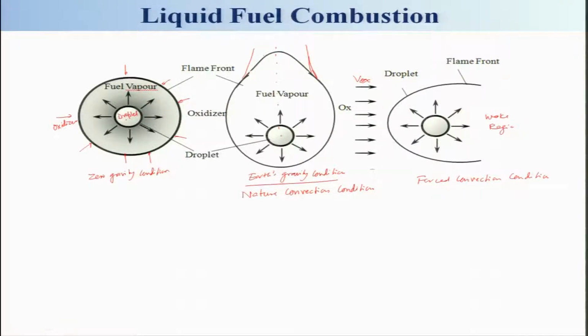And keep in mind that this distance, if I take from the center, or maybe I can take from center here. So, this distance, what I call, is the flame standoff distance, RF is the flame standoff distance. This is very important, and that will affect basically how fast the droplet will be receding, meaning getting consumed, right.